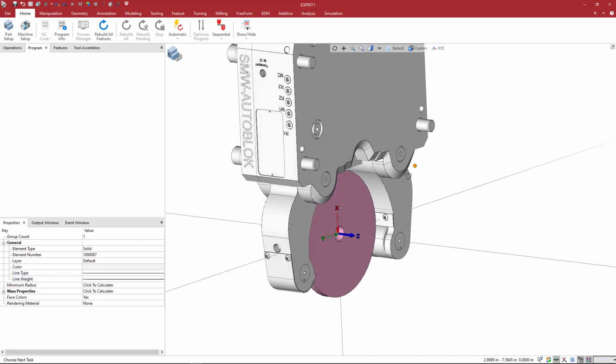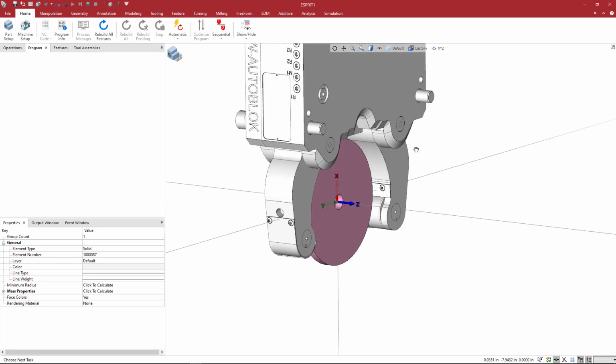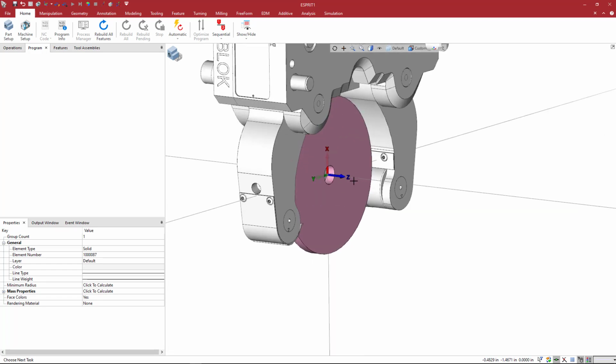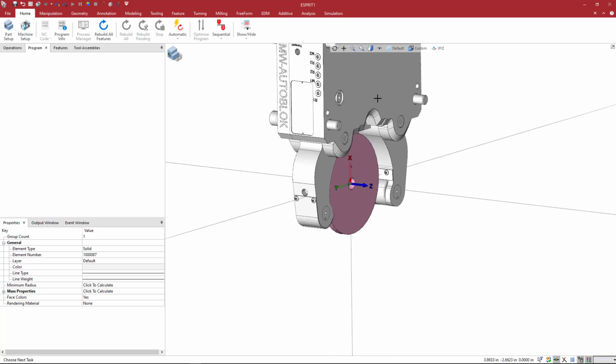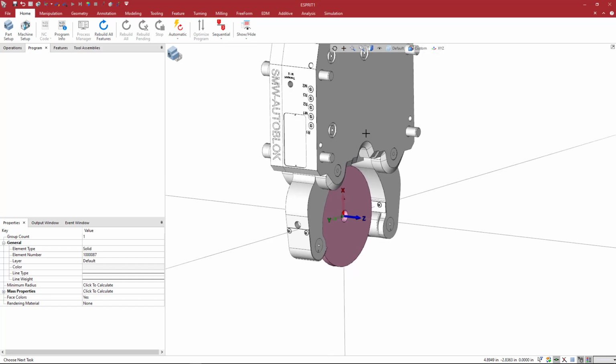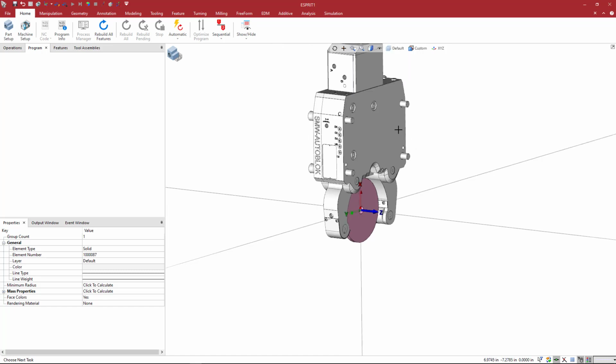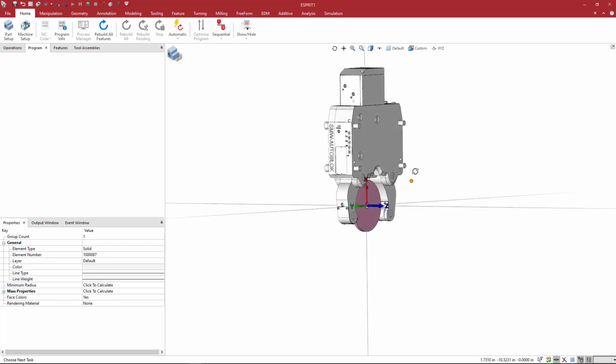If we had a standard smaller lathe, it would be like this. So looking at the solid model for this SMW Autoblock, it's basically 180 degrees from the orientation that it needs to be, because this would be upside down. I mean, we're not going to have a steady rest mounted on the top of the machine. This needs to be basically mounted at the floor.